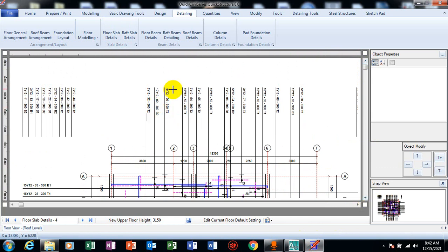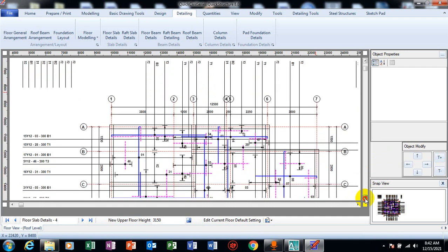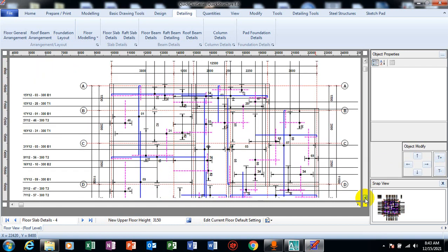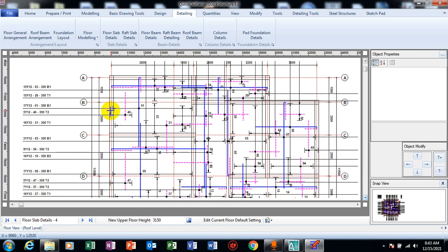Okay, now you can see the spacing is giving you 8x12, 32 the bar mark, 300 spacing, T2. That is, your T2 means top distribution bar. Okay, we have bottom 2, we have T1, which is your top bar. Okay, so this is bottom, top. I believe you understand all of that. That is how it details for you. The detailing is actually very great.